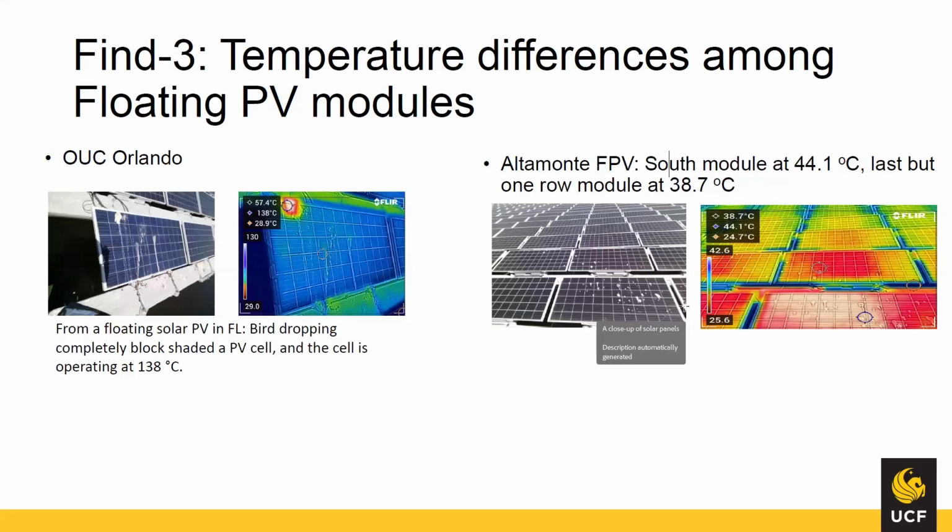And at least in Florida, it seems like they get enough rain events to mostly take care of the soiling that I've observed. But Windsor is still out there and doesn't get enough rain and does not see any cleaning. They do have a soiling sensor, but like I mentioned, that's in the middle of the array where they're not seeing the hot spots of soiling. So I'm not sure if they're getting the accurate information to be able to send a team out when they need to be cleaning.